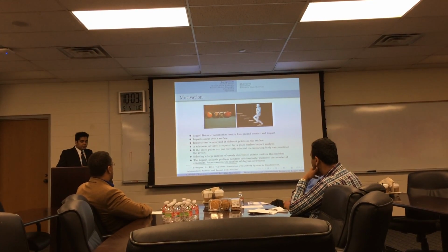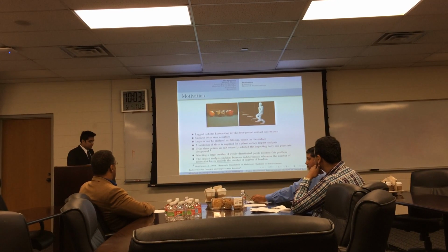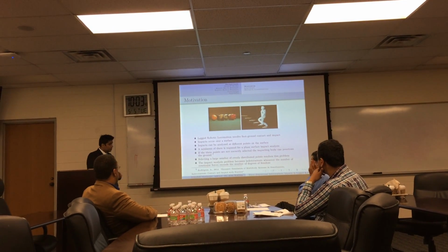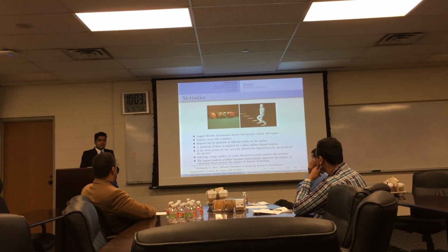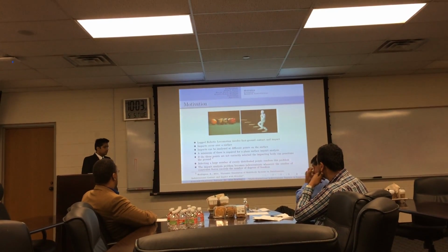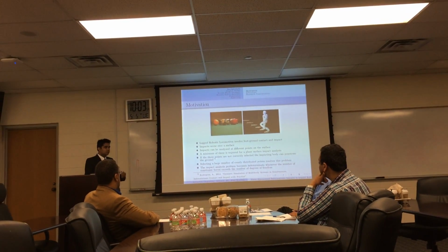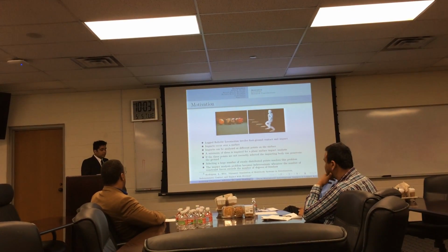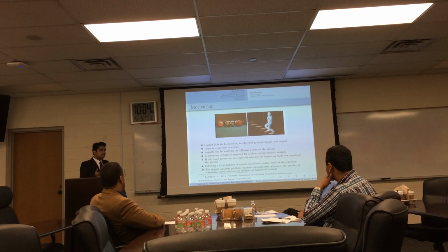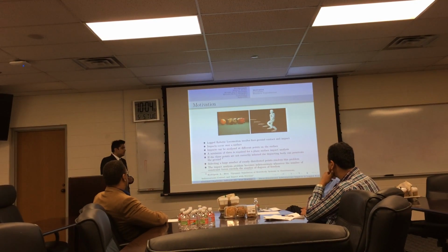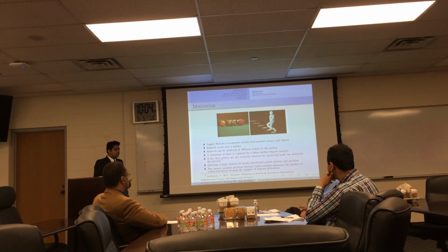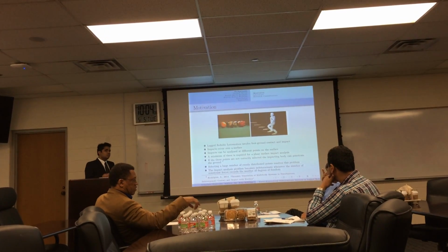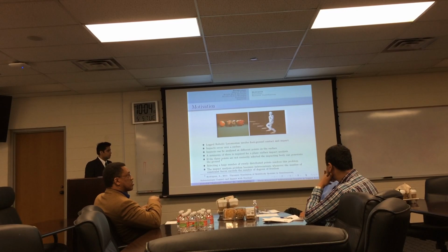Now, every time we add an additional point for analysis, we are adding an additional 3 constraint forces in the equations of motion. And if the number of constraint forces exceeds the number of degrees of freedom, then the impact analysis problem becomes indeterminate, which means we are trying to solve for more constraint forces with fewer equations.